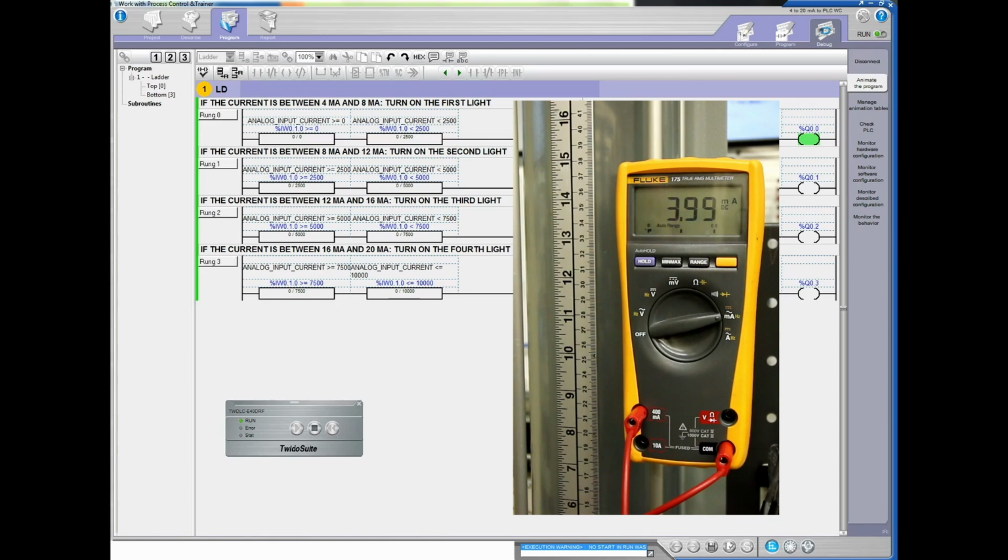But this is pretty cool, man. We've been able to increase the level in the tank here, so again we'll increase the level in the tank. We have a current that corresponds exactly to that level. We have a 0 to 10,000 range that's now turning on sequential lights. So now our second light turns on here. Beautiful. Going a little bit higher now, we're going to get to the 50%. Once we pass the 50% at 30 centimeters, then the third light will turn on right now. Gorgeous.